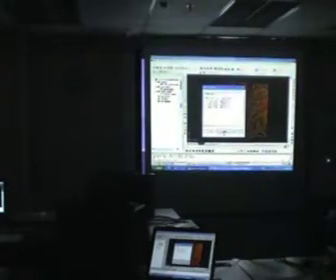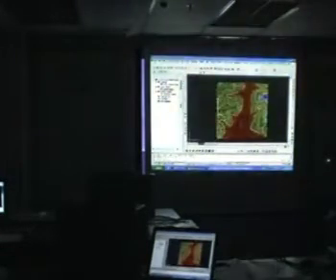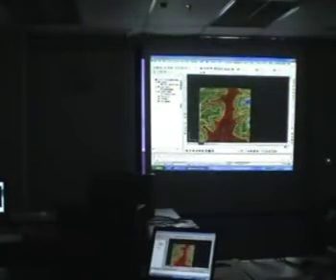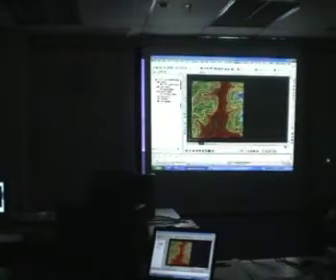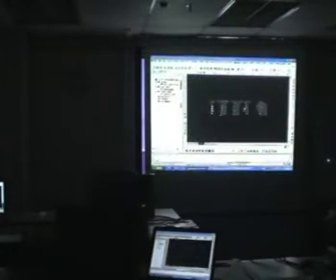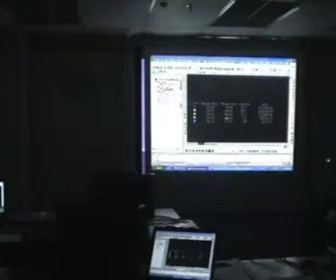You can even put a legend if you like. I'm just going to click legend, so OK. You can see how the colors are really being shown. So the red color indicates the lowest elevation, remember? Then followed by yellow, green, cyan. The legend is just going to be inserted here. When you zoom in, you can see, okay, this is the legend which you can use. The color is red, this is the range, the percentage of the area, and what the area total is in square meters.